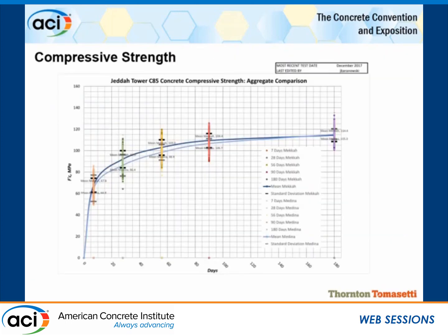But here's what's happening with the strength. So our 85 megapascal concrete, 12,500 PSI concrete, is routinely testing out at about 115 megapascal. So it's 85 megapascal in name only. It's really a higher strength concrete than that. And you can see the strength gain here. We're testing all the way up to 180 days and even 365 days, honestly. But we have no problem whatsoever with strength.